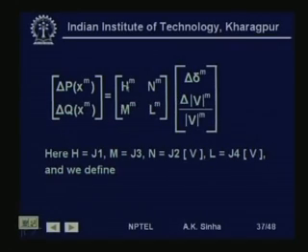Then all the off diagonal elements for this matrix and this matrix, this matrix and this matrix, they will come out to be the same terms, and therefore, the number of terms that we need to compute for the Jacobian elements gets reduced considerably. Also, if we are multiplying these two submatrices by v, then we are dividing by v this state variable term here for the Newton-Raphson algorithm.